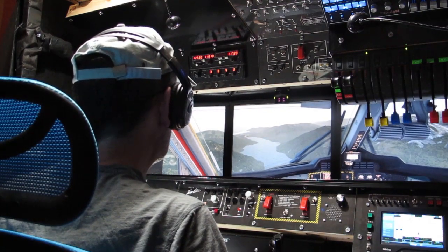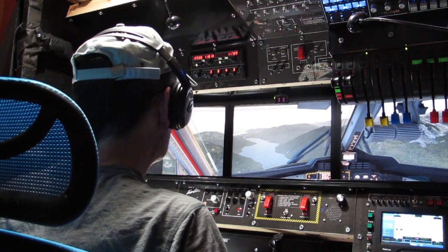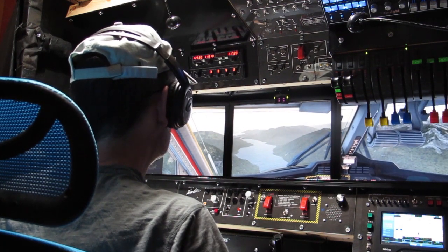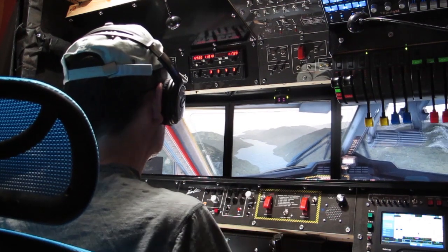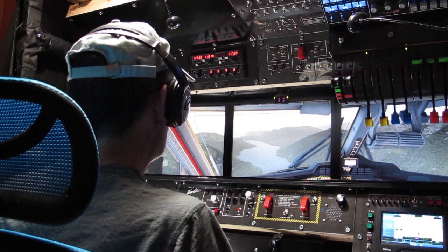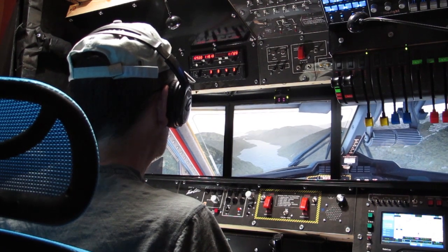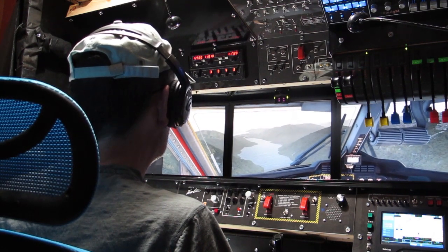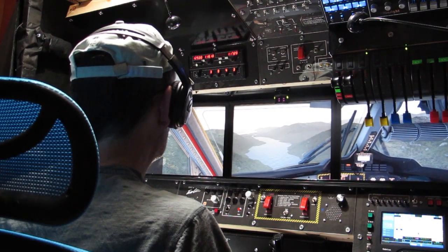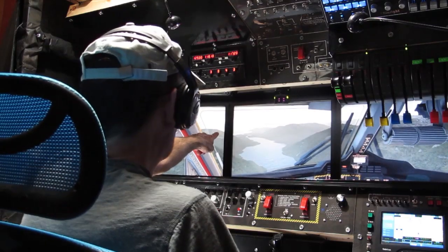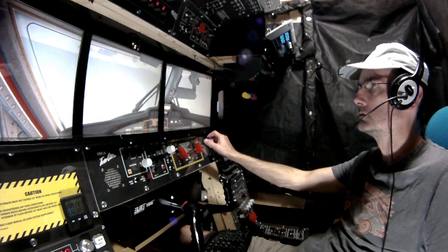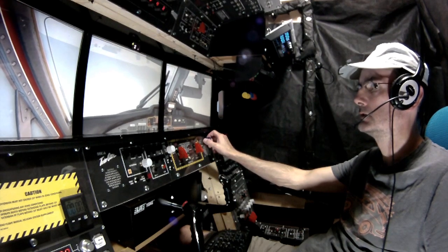So this strip runs 02/20, so the headings we need to remember are 20, which is the landing, we're hoping to land in that direction. Crosswind is 29, downwind is 02, that's over the ocean. Base leg is 11. The base leg has to be a little bit curved because this hill is going to be in the way. Whoa, where did the visibility go? Oh, that comes back.